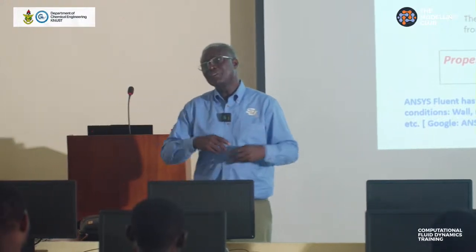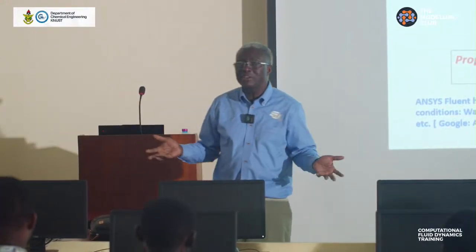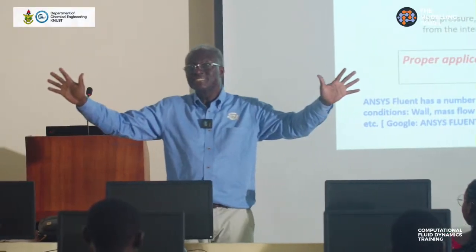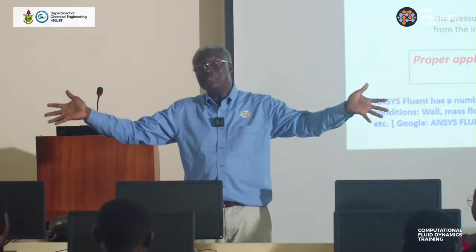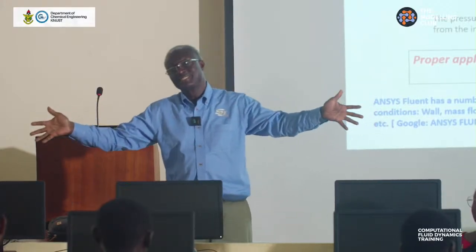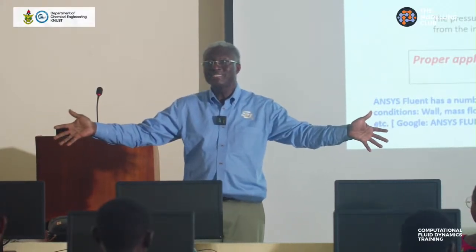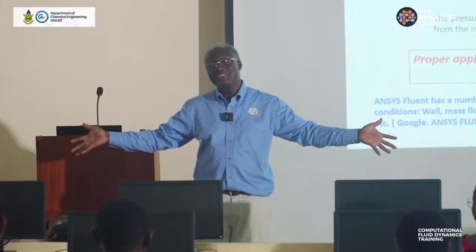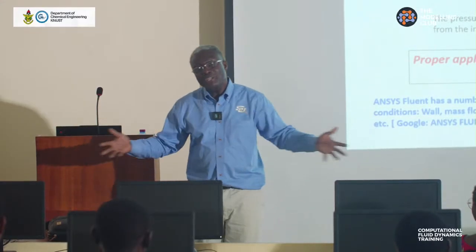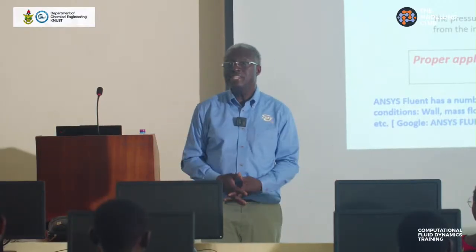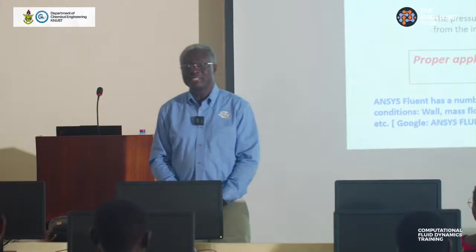But solving the Navier-Stokes equation for the sake of solving, like I said, you have what? How many equations? You have five equations. How many unknowns? 6. Can you solve that? No. Okay? No, you can't. So you can only solve it by introducing some constitutive relations to help you solve it.